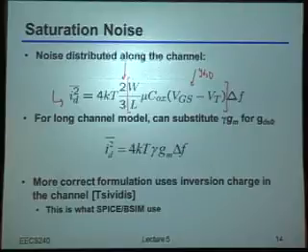So in particular, what we're basically doing is we're saying that because now the channel charge is not flat anymore, it has usually this kind of triangular-ish shape. And by the way, because it's a triangle, you can roughly guess why it would be a 2/3 factor there, just when you do the integration. What we're basically saying here is that, because it has that triangular shape, what we can essentially do is just substitute gamma GM for GDS naught.